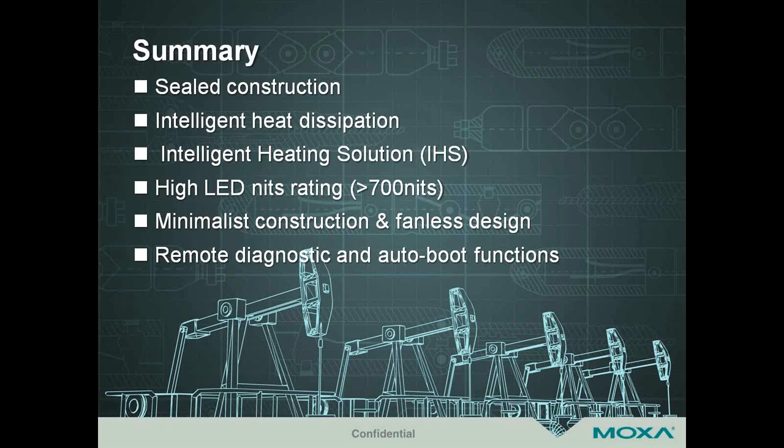Oh, no, these panels are constructed to be operable in direct sunlight. That's one of the things that we actually call out as a definitive design feature and functionality that any industrialized panel or HMI should have, and that being it should have the high temperature grade, at least up to 50 degrees Celsius, which is more or less 140 degrees Fahrenheit, or even higher than that, I believe.